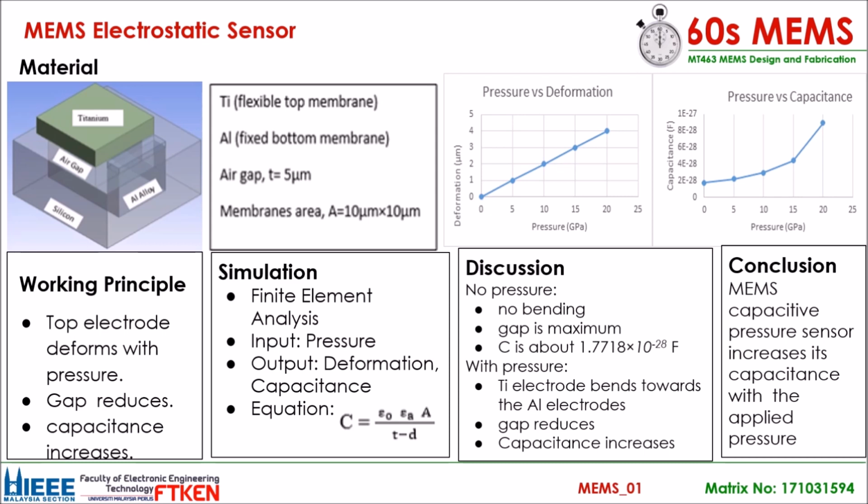The simulation uses finite element analysis. The applied input is the pressure. The output is the deformation. From the deformation, the capacitance value can be obtained through this equation. From the graph, it can be shown that the capacitance increases with the pressure applied.